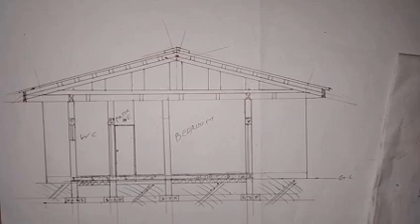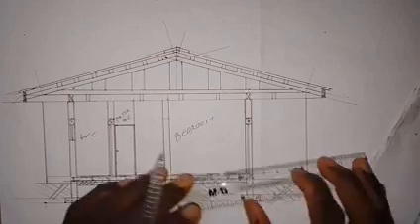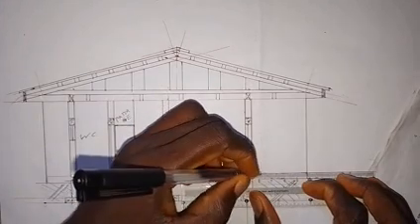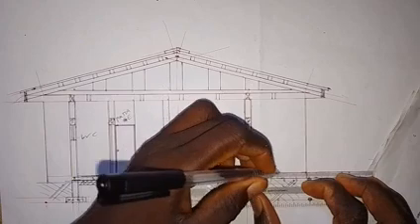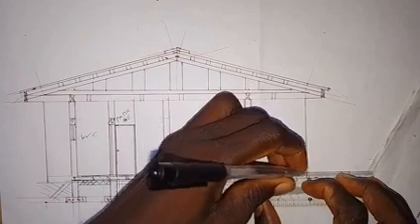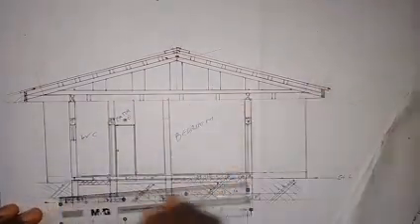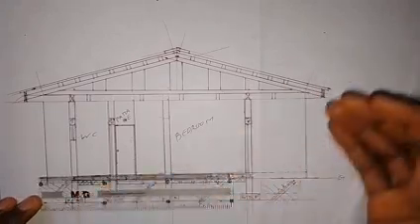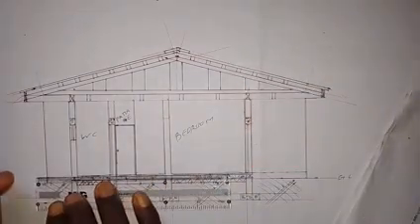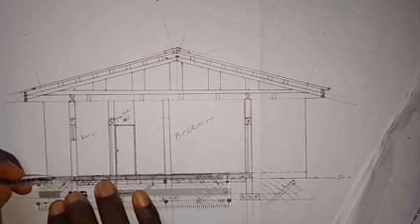And then I also need to, for this floor level here, we can't see it, so let's show it hidden with short dashes line for this floor level within this veranda. Though we can't see what is there, because there's a wall here that prevents us from seeing what is inside the veranda. Also this is within a building, so we need to show this hidden.